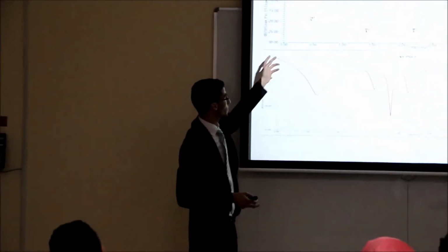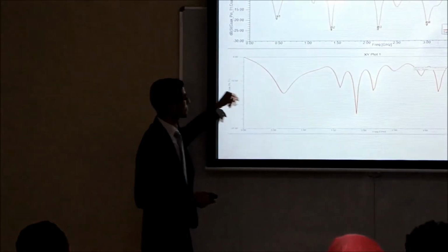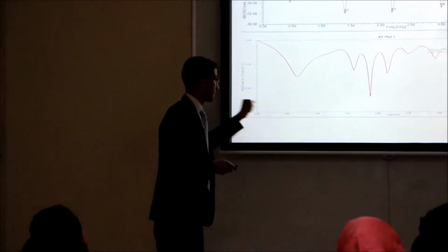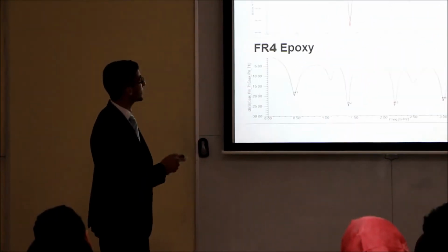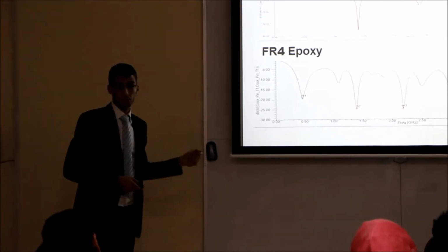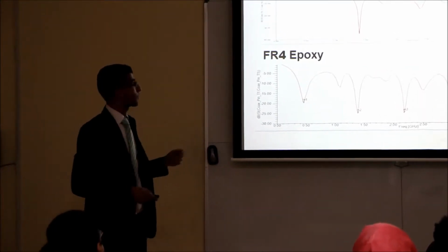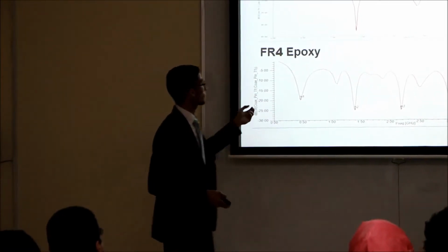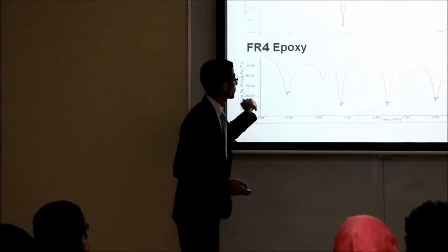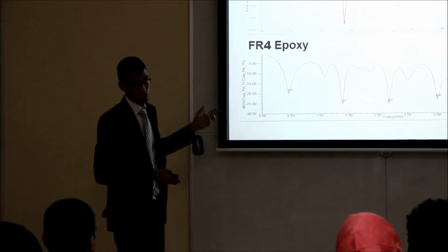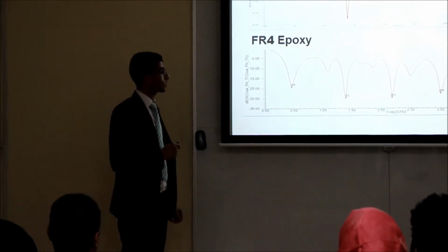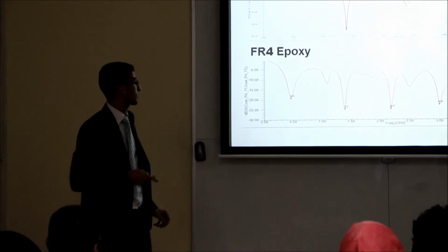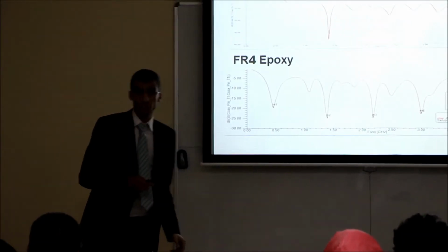As you can see, the different resonant frequency shows up in different places. Same thing applies for a different material, where we tried the material that was suggested by the literature, called Rogers RT. It showed different performance, where the first resonant frequency showed up at around 1.4 gigahertz, which is not suitable for our application, which is partial discharge detection. Now I'll leave you with my partner AbdAlmonam.